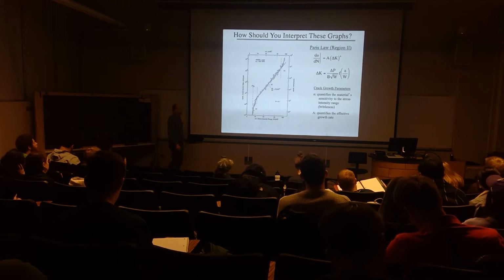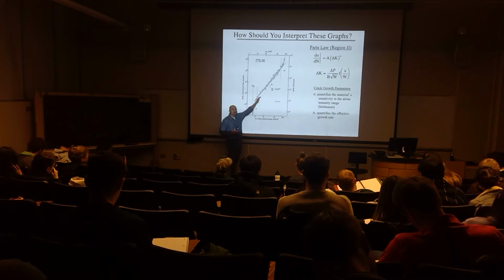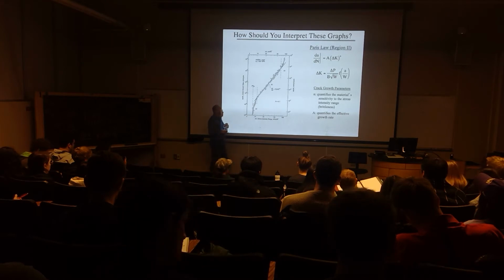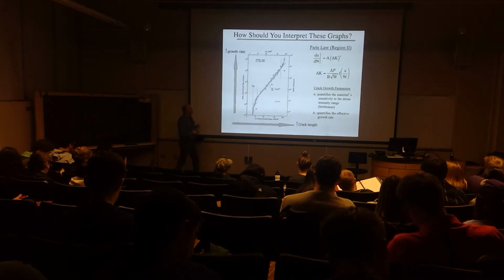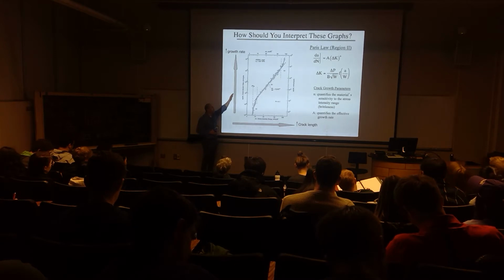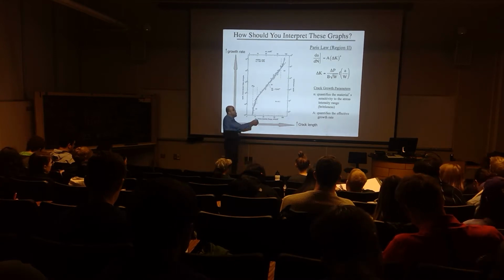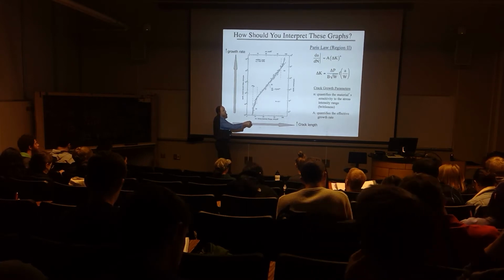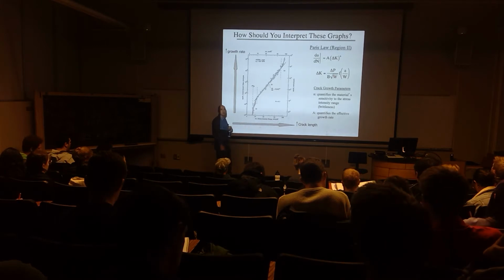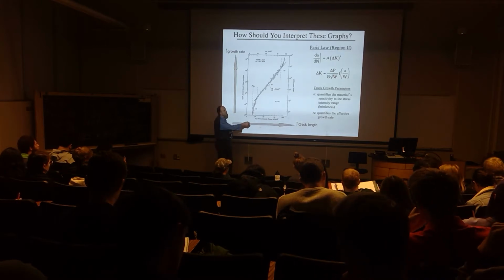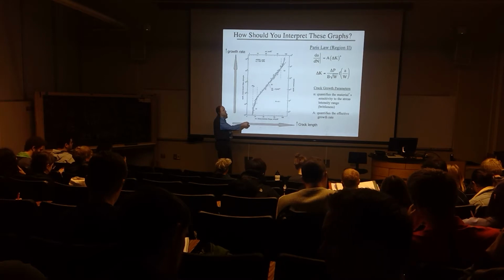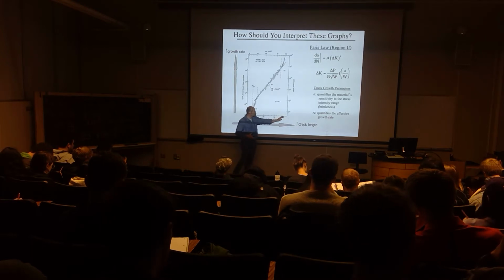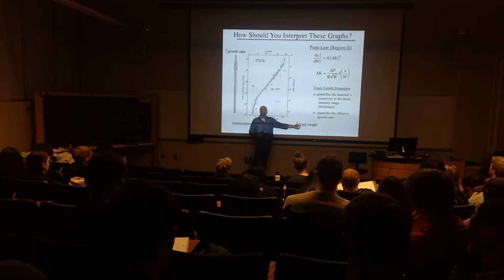First, I want to make sure that when you look at a diagram like this, you're prepared to think about what it means physically. First of all, this represents the growth rate, and this represents a function that's primarily changing with the crack length. These quantities, the specimen thickness, the specimen width, etc., are geometric constants. So the only thing that's changing in this delta K relationship is the crack length. This says that the stress intensity increases as the crack length in the structure increases.